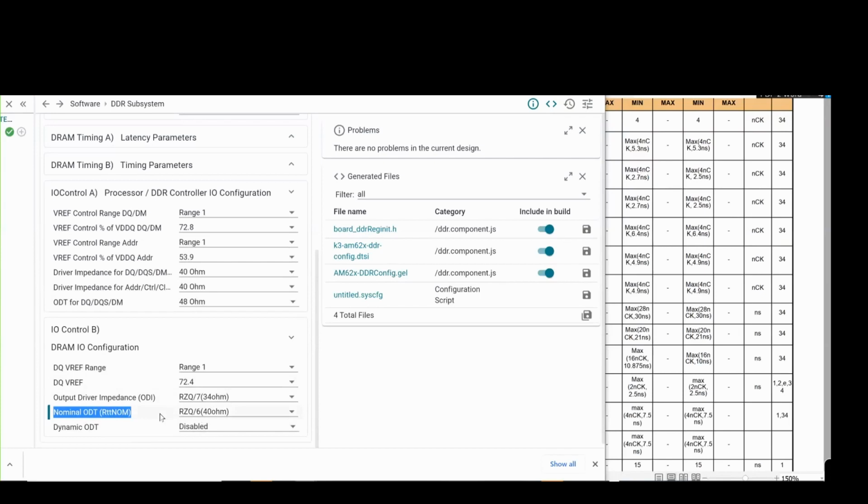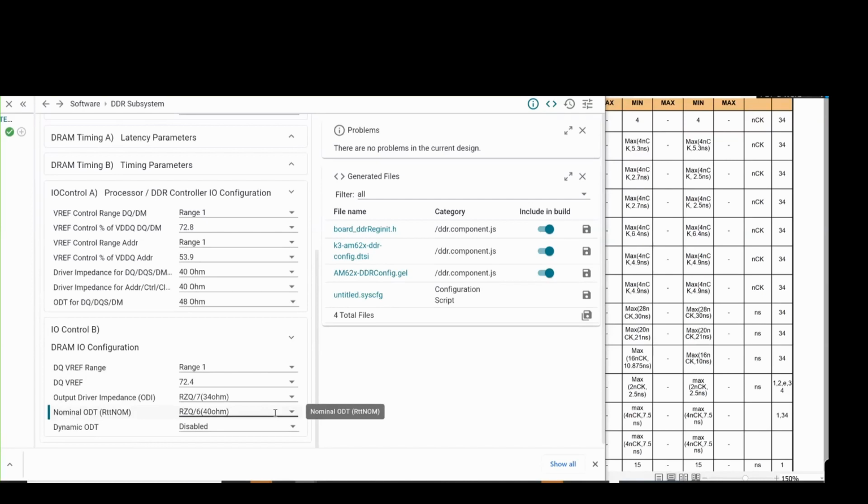They're actually different for LPDDR4. So this is just the way the I/Os are configured specifically for DDR4. The data sheet does have information about how the termination is implemented, but the actual choice of the value comes from your board simulations. That's a whole other training session on how to do these board simulations for different designs.